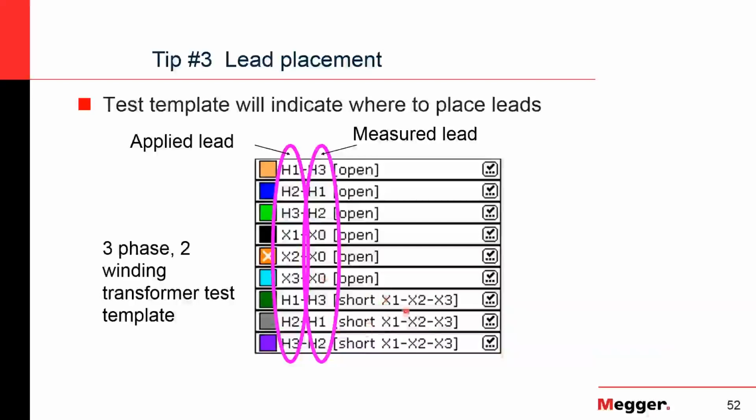The next thing, and this is very important, is the tap changer position. One thing about SFRA is it's a very sensitive test, which is great because you'll pick up little problems inside your transformer. But the other thing, because it is such a sensitive test, you can actually influence the results, and anything you do can change the results as well. So you want to make sure that you're always indicating, like in your test report, in your test file, what the tap changer positions are.